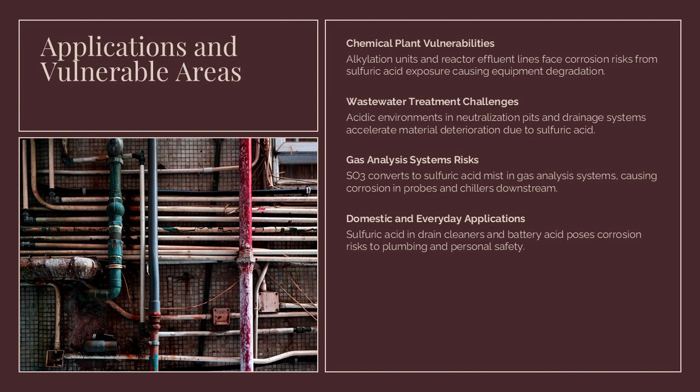Wastewater treatment plants face constant exposure to acidic environments in neutralization pits and drainage systems, where sulfuric acid can accelerate material deterioration. In gas analysis systems, such as continuous emission monitoring systems or CEMS, sulfur trioxide or SO3 converts to sulfuric acid mist as hot gases cool, causing downstream corrosion in probes and chillers.